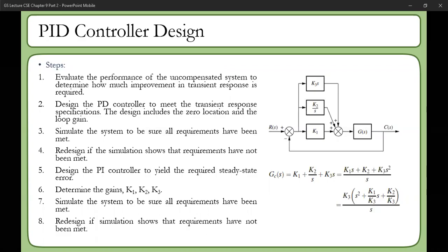For improvement of the steady state error, we are not shifting the root locus. We are just introducing a pole at the origin and a nearby zero, so it is almost at the same location. But for improvement of the transient behavior, we are shifting the point to a different location, so we are reshaping the root locus. So which one is better for us to implement?